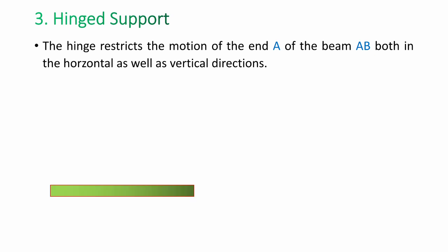So in this case AB is the beam. Next, it is hinged with a special device, inserted with bolts. I made that a hinge. The other end I am going to keep on a roller support. Now you tell me, the hinged support at A, what kind of motions is it going to restrict? That depends on what type of forces are acting on that member. In this case the P force is not acting in the horizontal direction or the vertical direction, so it is going to be in an inclined direction.